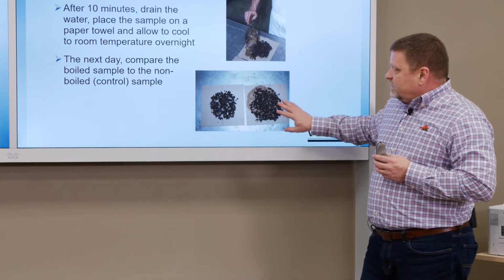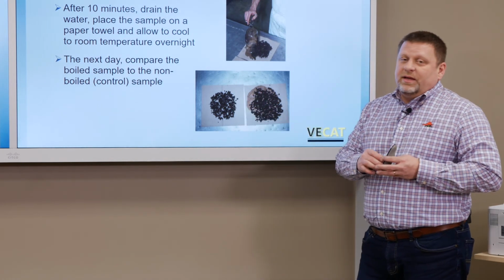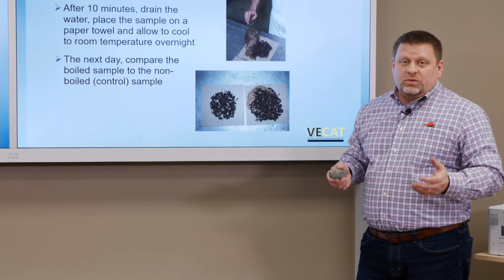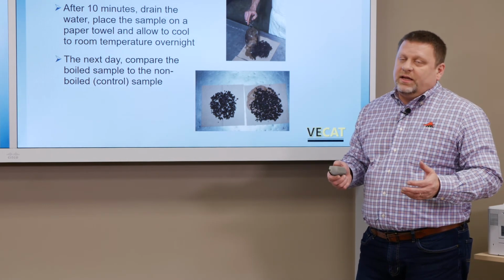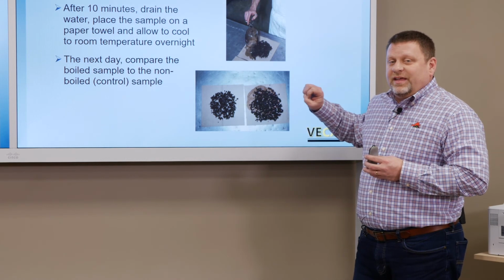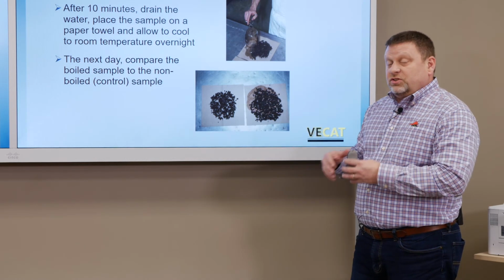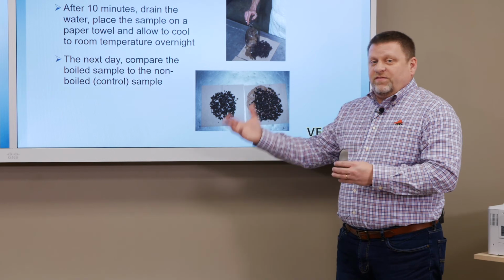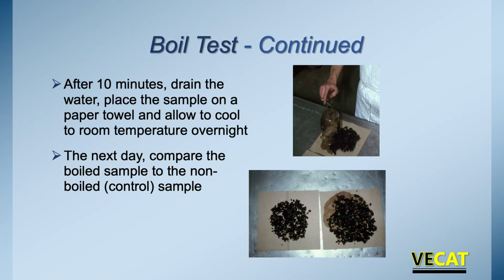So if I have this image, what I would recommend, we all have cell phones or digital cameras now, they're very common this day and age. I would take a digital image of this sample that gives me a boil test that you saw I just performed in like 25 or 30 minutes. That gives me a visual image of what passed my TSR. Now I have that image, I would print it out or save that image for any future testing.